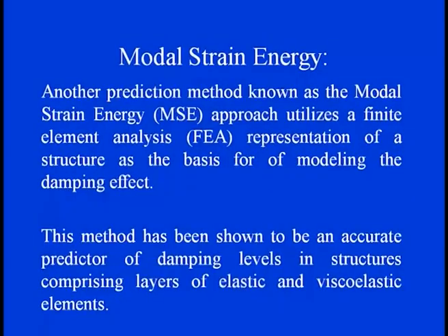The second approach is the modal strain energy. The method based on the modal strain energy is utilized for the finite element solution of such problems, in which the entire element is discretized into various elements, and then this method provides an accurate predictor of the damping level, which comprises various layers with the properties of elastic and viscoelastic elements.